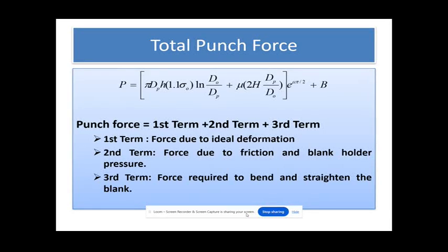Punch force can be determined using this expression. Here, the first term represents the force requirement for ideal deformation. The second term represents the force requirement due to friction and Blank-Holder pressure. The third term represents the force requirement for bending and straightening of the blank.